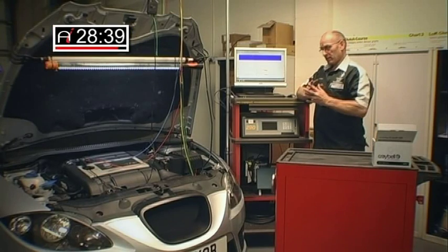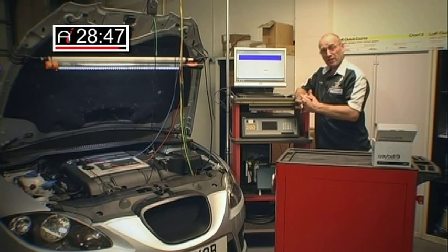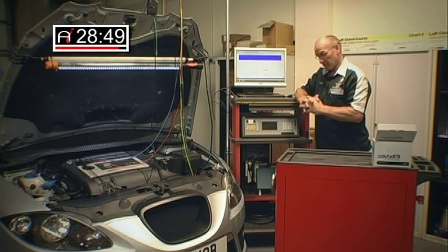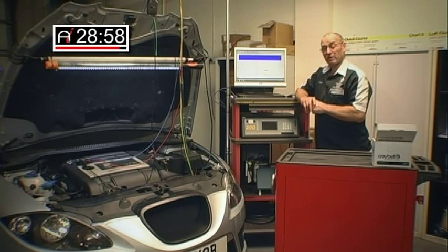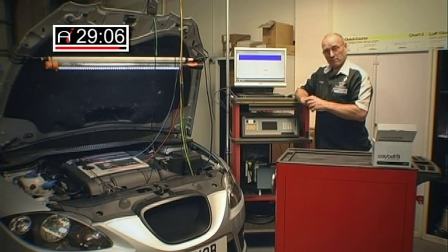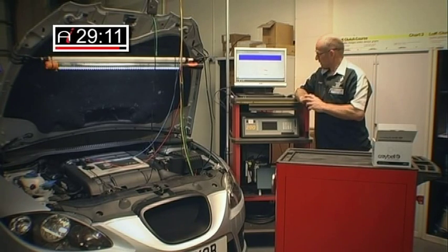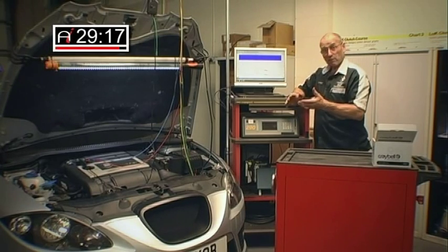I did make the point that to test an air mass meter thoroughly through the entire operating range, you should load the car, either on the road or on a dynamometer. However, even under workshop conditions, a static car, we have found these tests incredibly accurate. And of course, you're comparing known data. We're comparing the exact condition of this system with another one. And of course, we store this data in our archives so that we know exactly how much current flow passes through this device and exactly what frequencies they are.